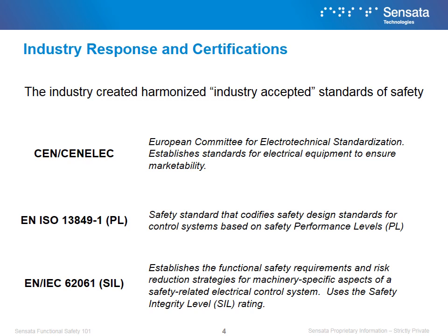13849-1 is the safety standard that codifies safety design standards for control systems based on safety performance levels that resulted in a calculated risk reduction. This standard is referred to as PL or PL rating.